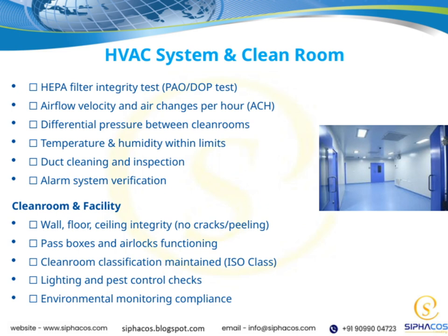We also monitor the differential pressure between clean rooms, which is crucial to prevent contaminated air from entering controlled spaces. Temperature and humidity are kept within strict limits, as variations can impact product quality and environmental stability.